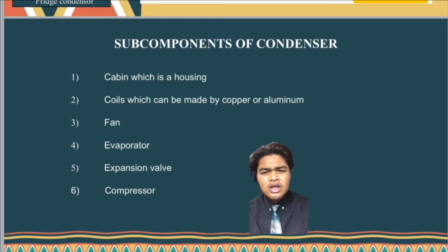Next, the evaporator coil is found in the indoor unit, while in a central system it is located in the air handler. And the purpose of the compressor, of course, is to compress the refrigerant, which is a warm vapor as it reaches the compressor, into a hot compressed liquid. In between the condenser and evaporator, there is another little gadget called the expansion valve. As the refrigerant is now a liquid, it will be unable to absorb the heat.